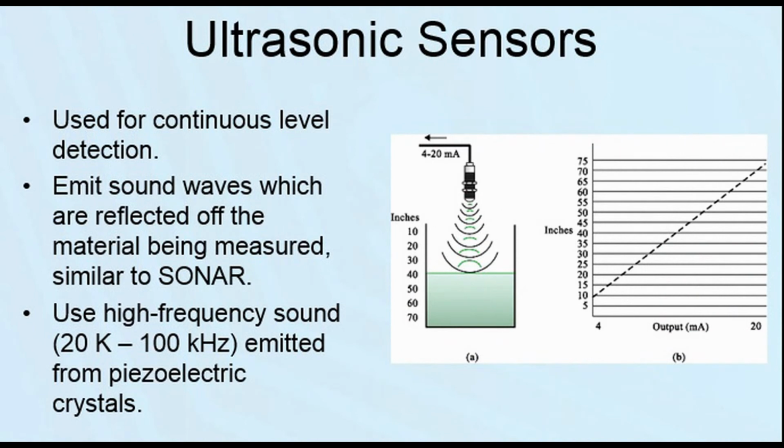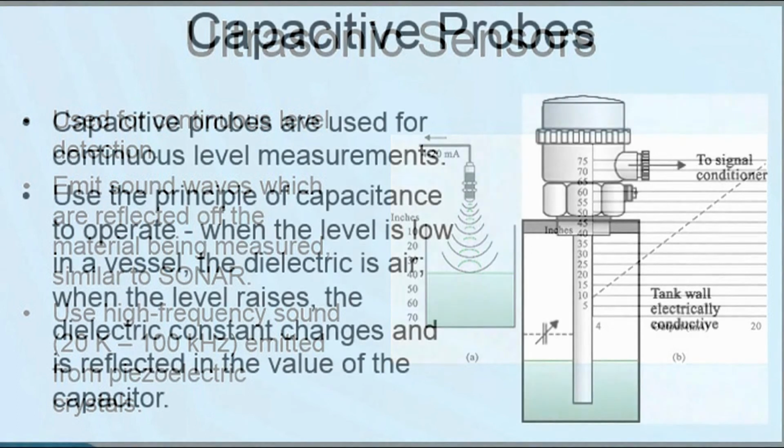Ultrasonic sensors are used when working with dangerous fluids that could be explosive because they are non-invasive and give a continuous measurement. The only problem is they could be susceptible to mist or fumes that form at the very surface of the liquid that's being measured.